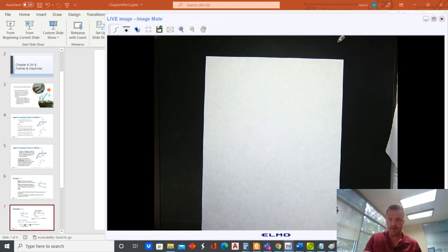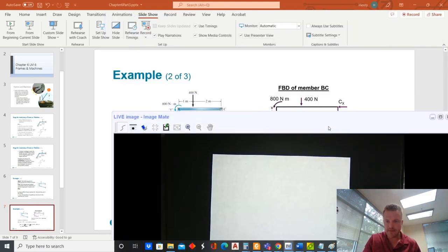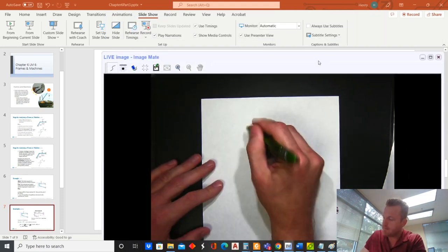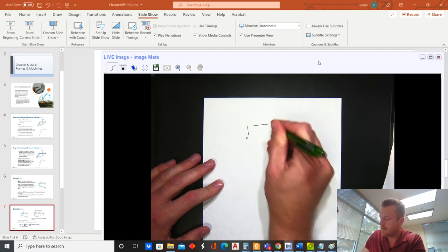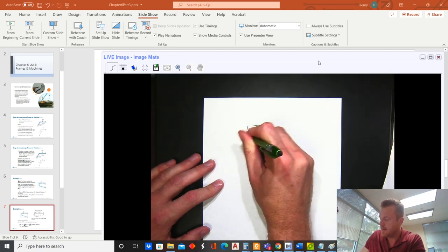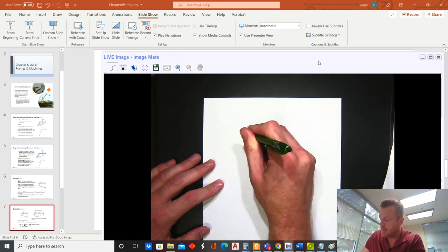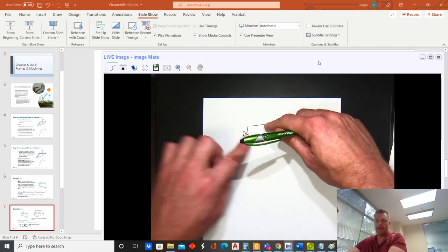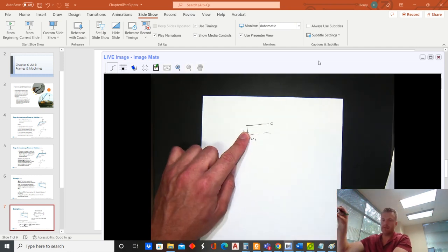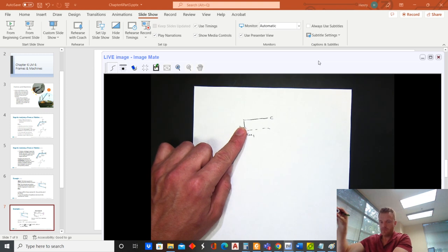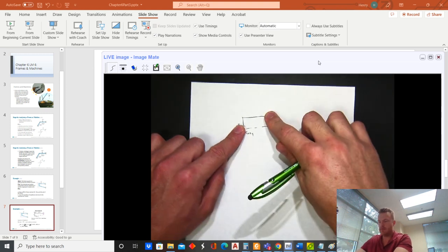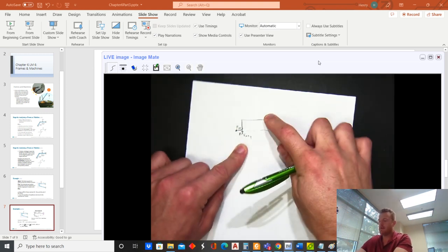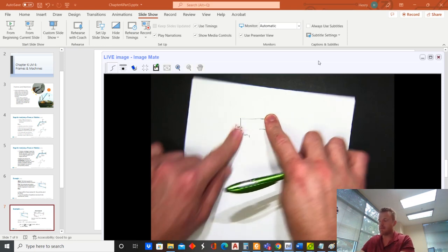So you had, let me make sure I'm using the same notation here, BC. So there's B and there's C. And if you decompose this into FABX and FABY, you'll notice if you pin at C, right, the X component, zoom in a little bit, X component will induce clockwise rotation, along with the Y component will induce clockwise rotation.